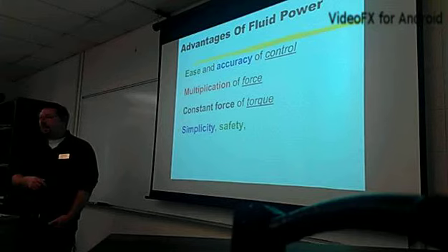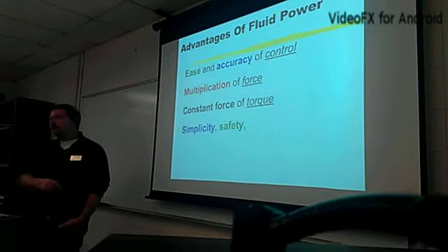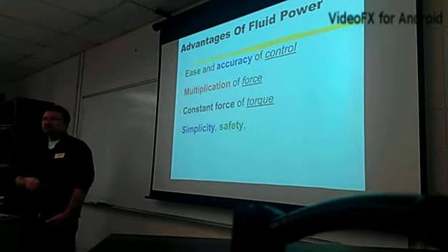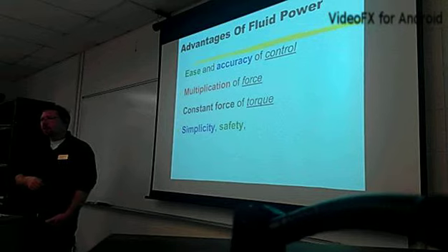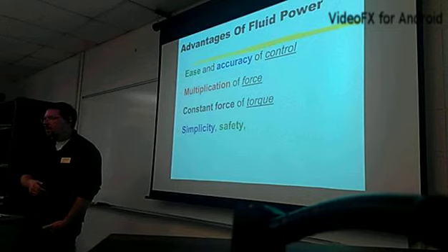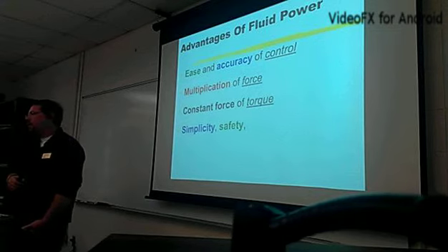Part of it goes back to maintenance. Very rarely does a hydraulic system just blow a hose. Usually, there's a small leak or a bubbling of something to indicate that it's fixing to go, and it should be fixed before that happens. But yeah, they can just blow, just like a motor can explode or a drive can blow up capacitors. With anything made by man, eventually it's going to fail if it's a mechanical or electrical device.